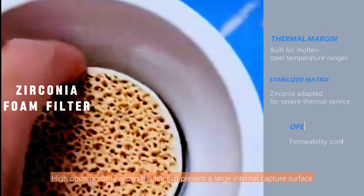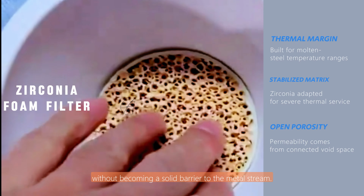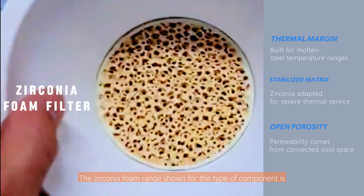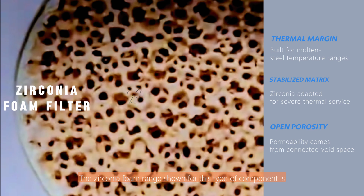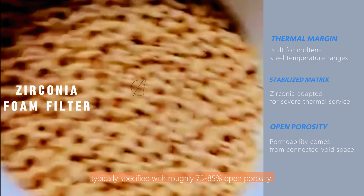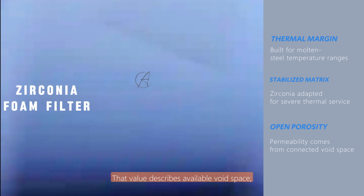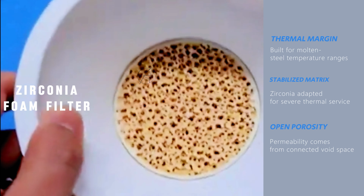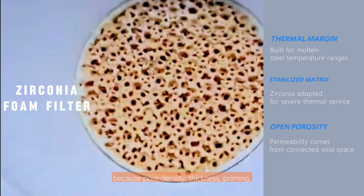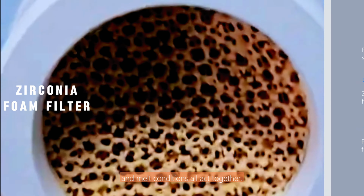High open porosity allows the filter to present a large internal capture surface without becoming a solid barrier to the metal stream. The zirconia foam range shown for this type of component is typically specified with roughly 75 to 85% open porosity. That value describes available void space. It does not by itself determine flow, because pore density, thickness, priming, and melt conditions all act together.